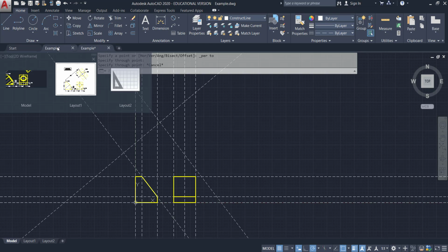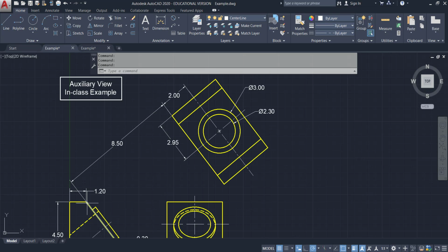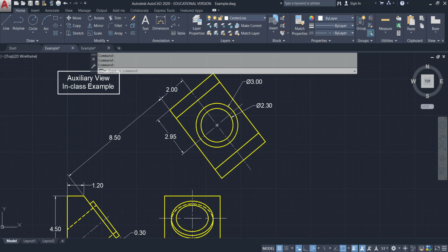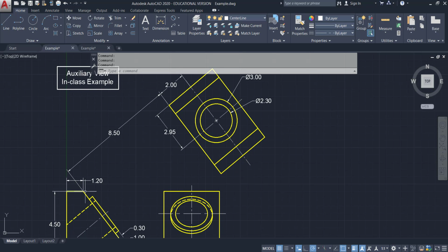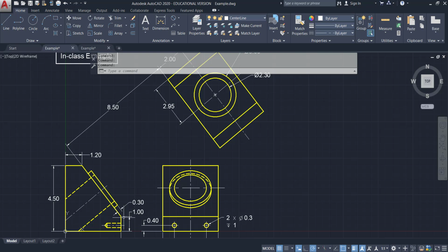And let's go back and look at the drawing. So actually this point should be lined up with this line here, and this corner should be lined up with this line here. In other words, any intersection point will need a construction line, and the same here and here. Because the dimensions are different, they're not exactly symmetric.